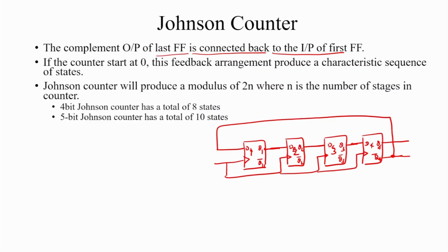Initially we clear all the flip flops, this means the clear input is applied. Whatever value was previously stored is cleared, because we know that when we supply a clear input to a flip flop, it does not depend on the input of the flip flop. When the clear input is 0, all the outputs are cleared, and whatever was stored, all become zeros.